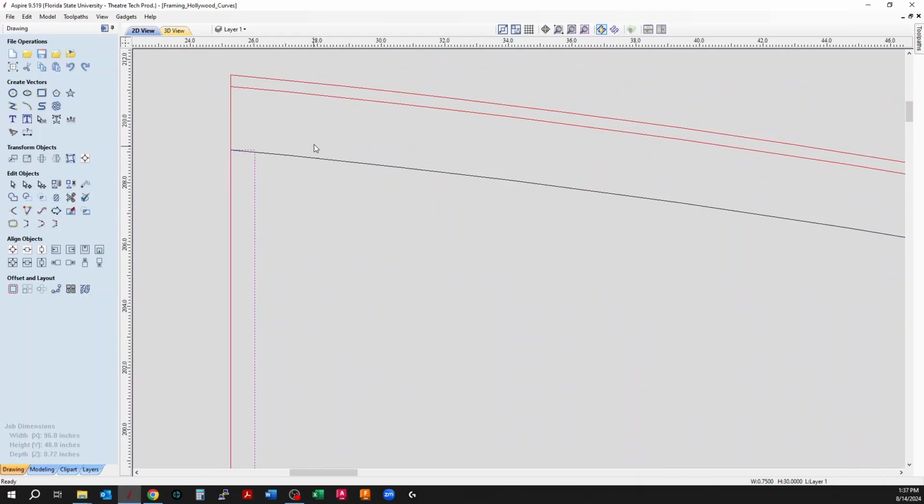So what I want to have happen, I've got about 2.5 inches right here of good solid framing material. I don't want to go much larger than that because then it just gets heavy, and I want to avoid unnecessarily heavy things. So I'm just going to inch this up a little bit here, and then I'm going to modify this piece. So going into my node edit tool, right, I can modify this so that it fits around the contour that I'm going to do here. And so I'm going to show you how to do that. I hit I to insert a point, right? And then now I want to extend this down here so I've got a bit more meat to go into.